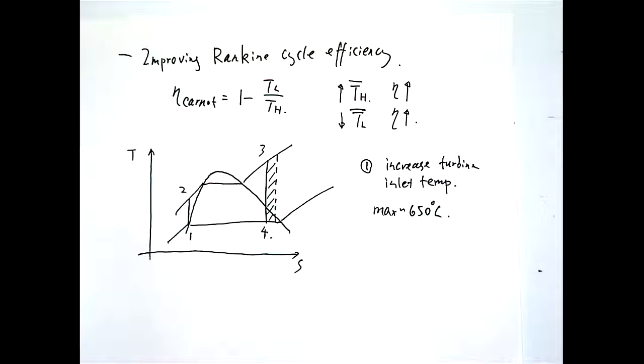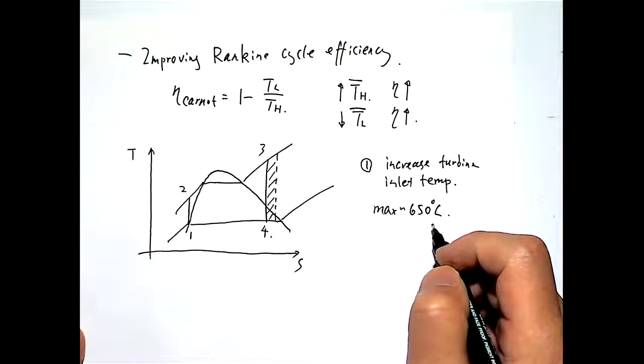So this heat transfer process limits the temperature at which the steam can be generated. And another consideration is steam is not an ideal gas. It can be corrosive, particularly under high pressure conditions, so it cannot reach as high a temperature as the gas turbine. But anyway, this is already being reached as a practical limit.